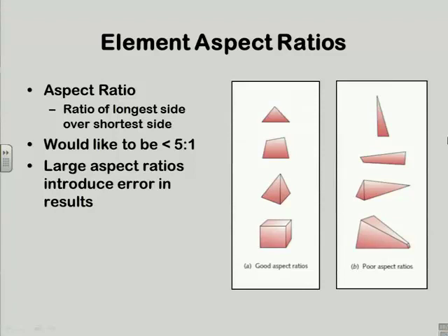Yeah, that's a good point, because you can't get information across the cross-section if you don't have multiple pieces across the cross-section. That would not be true of line elements, but then line elements are not going to give you as much info. For solid elements, yes, you're right. You don't want one layer of bricks through your beam, is what he's saying. You want several layers of bricks, which makes perfect sense. Thank you.